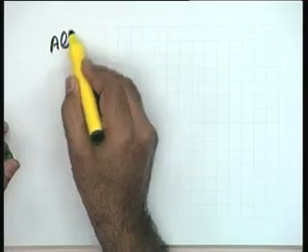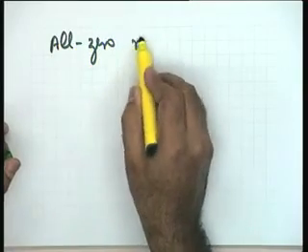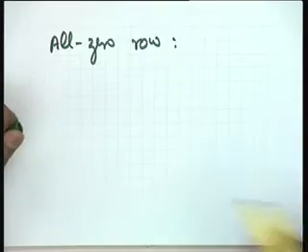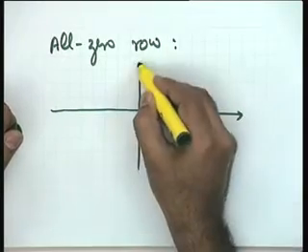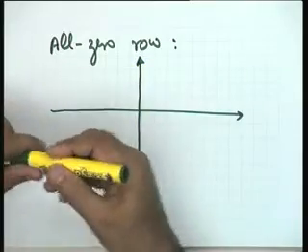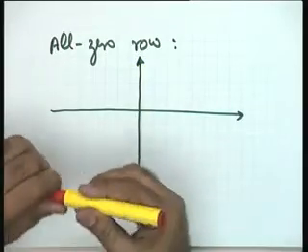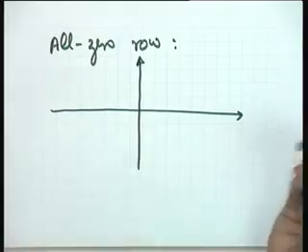Maybe in another example a row earlier than this row may appear. So, what I am referring to, any row in the Routh array, if it turns out to be a 0 row, in that particular case the possibility of j omega axis roots exists. In fact, if you come across an all 0 row, again without proof you will have to digest the statement. In that case one or more of the following will happen. See all the possibilities which could occur, one at a time or more than one at a time.